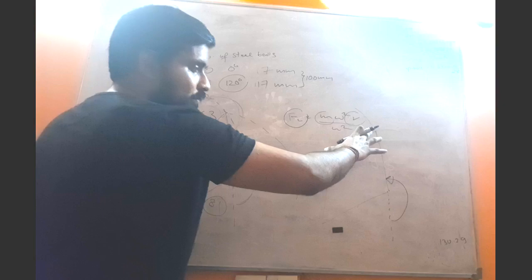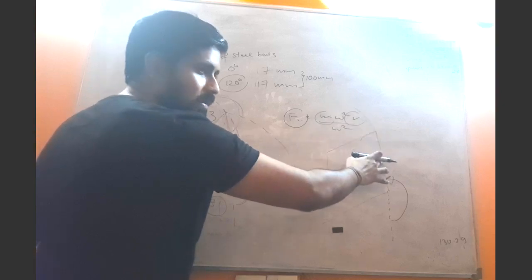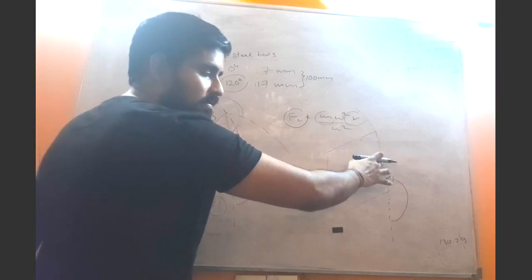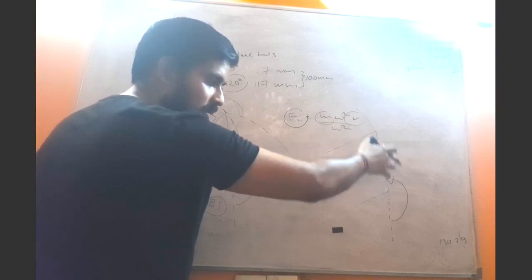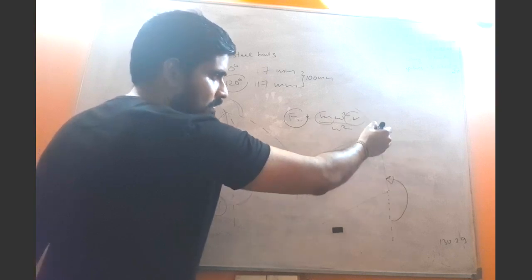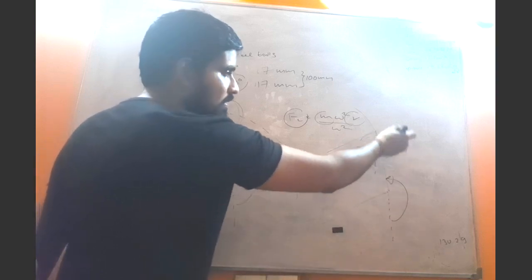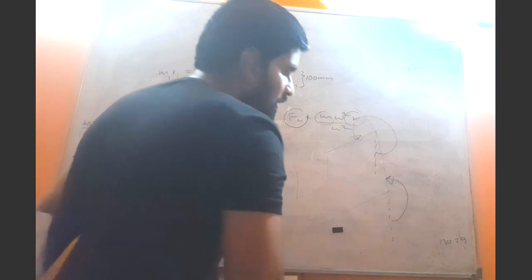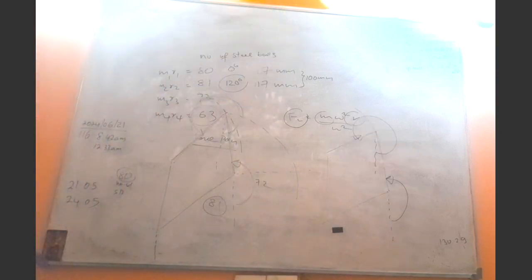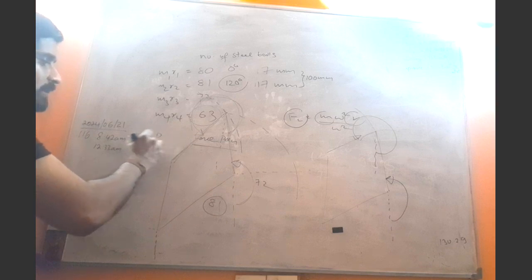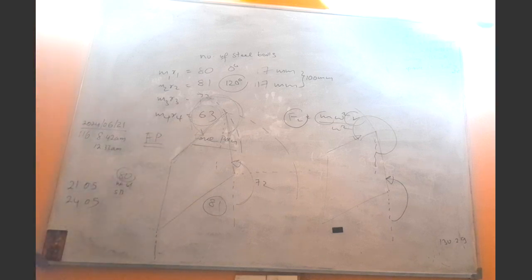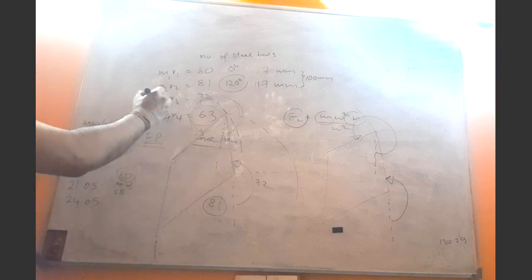When it comes to the fourth vector, go to the previous vector where the sketching has ended. So the previous vector is the third vector. Again sketch a downward vertical, then start measuring from the downward vertical, like that, right? So I hope now we got it right. So now from the fourth polygon you can find the other respective angular positions, right? for the third mass and the fourth mass.